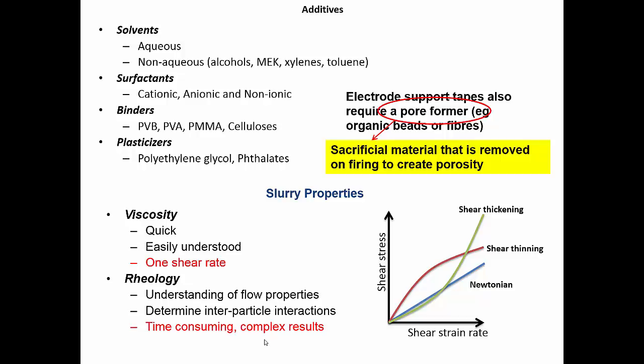So for the slurry properties, we are very interested in the viscosity and the rheology, and what we really want to be working in, if we can help it, is a kind of Newtonian region whereby we've got linear shear stress, shear strain characteristics.